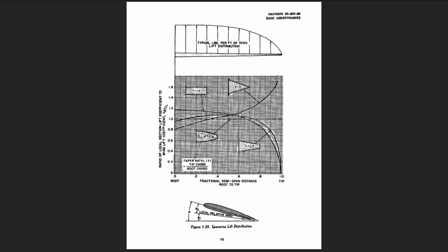If the planform area distribution is anything other than elliptical, it may be expected that the local section and induced angles of attack will not be constant along the span. A planform previously considered is the simple rectangular wing, which has a taper ratio of 1.0. A characteristic of the rectangular wing is a strong vortex at the tip with local downwash behind the wing, which is high at the tip and low at the root. This large non-uniformity in downwash causes similar variation in the local induced angles of attack along the span.